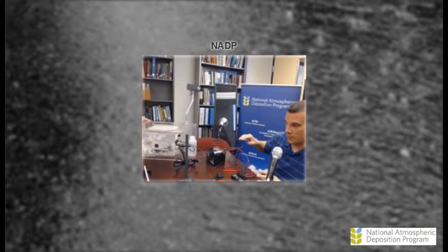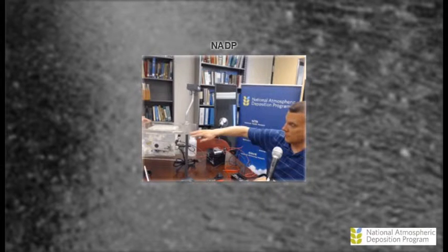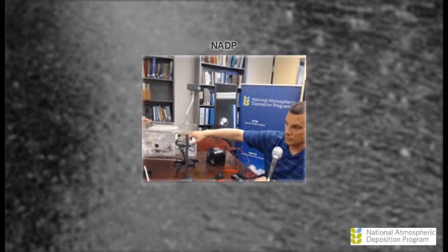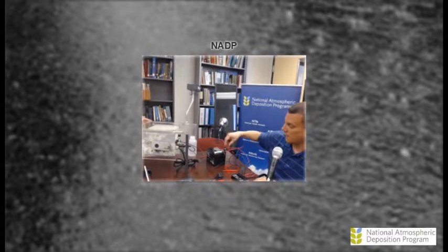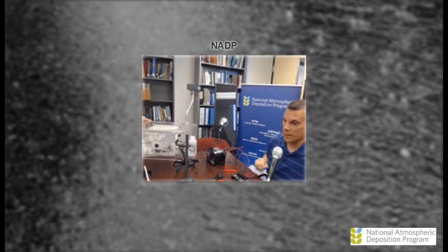So a few things to note. I'm not showing the ground here, but we have fusing at the collector. There's the built-in cartridge fuse there, and we have an inline fuse for the battery. And we'll talk a bit about how we do troubleshooting there. So let's go back to the PowerPoint presentation, if we could, please.